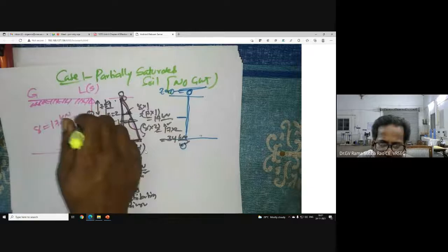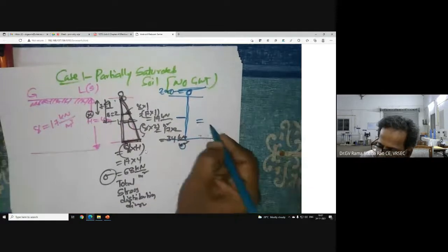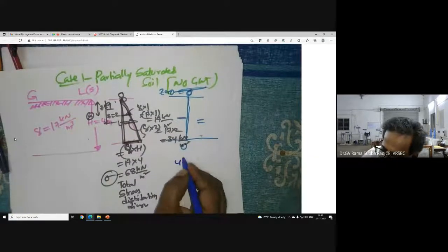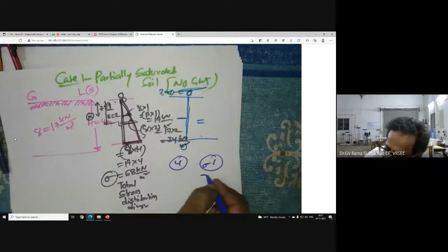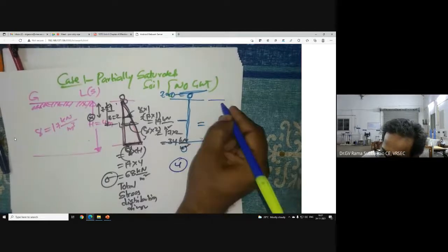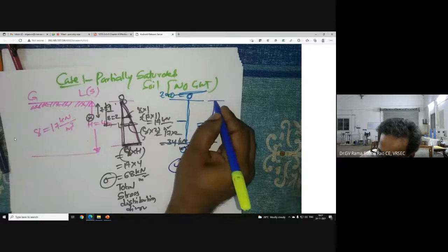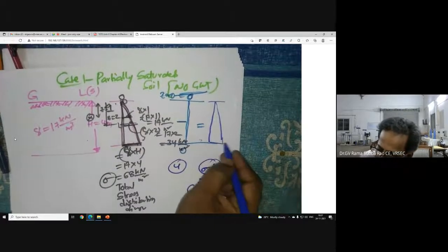If we insert a piezometer, it shows 0. So now the head of the water is 0. So altogether, I'm getting the answer now. This is the pore water pressure distribution diagram. My interest is to calculate effective stress, sigma dash is equal to sigma minus u. Now it is the time to draw the final diagram, the actual pressure distribution diagram, that I am trying to call effective pressure, also called intergranular pressure.